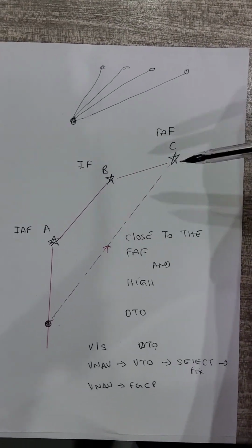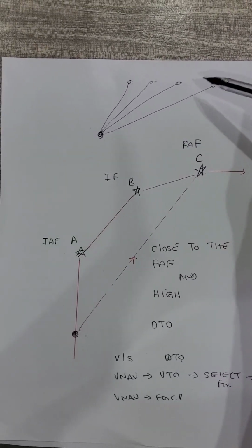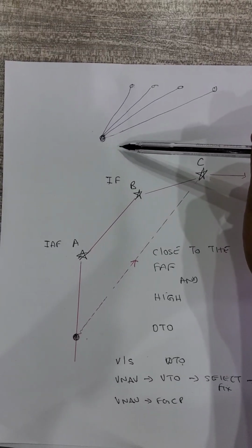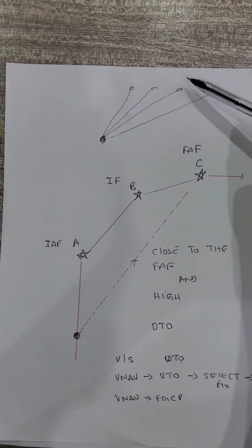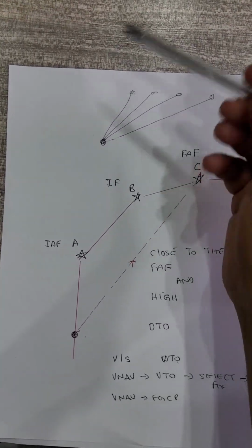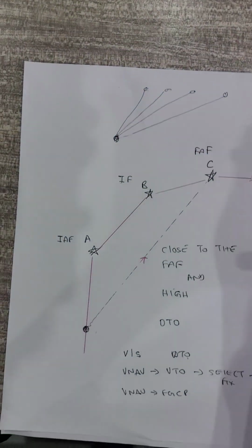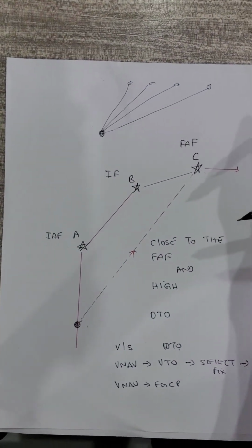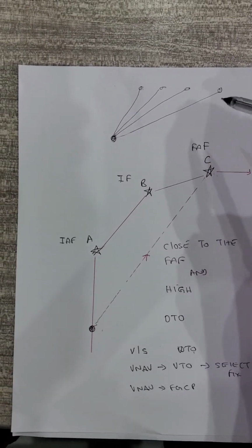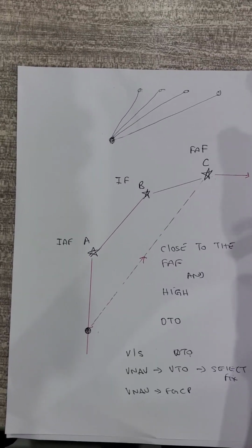Okay, so this exercise which I've just shown you also depends on the actual distance you are. Until a certain distance the FMS will be able to calculate, but then it will itself say, this is too much for me, I cannot do it. Okay, and obviously if you are on top of the fix, you want to go down, I mean, you're not a helicopter, you're an aircraft, so it's impossible. So that is something to bear in mind, all right, when you are reprogramming the vertical profile in the FMS of the Dash 8 Q400.